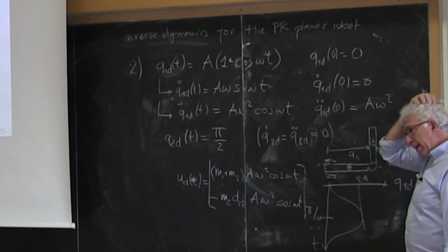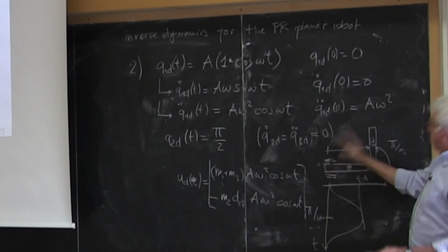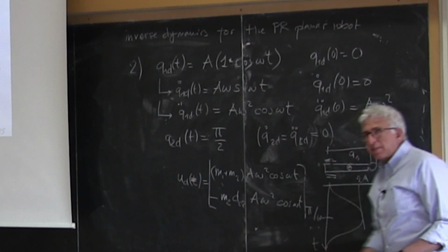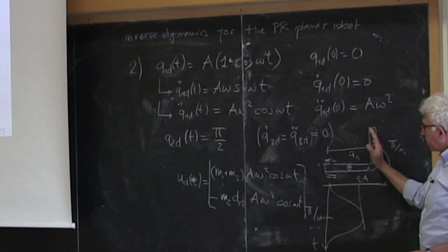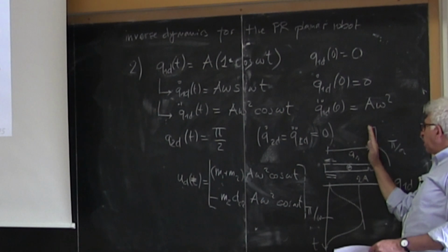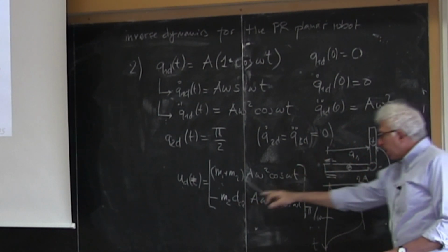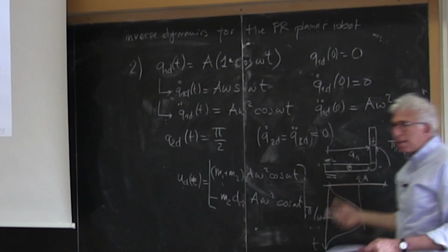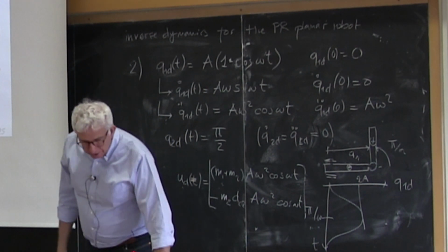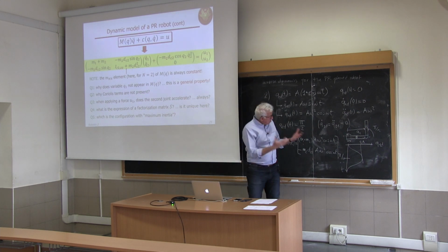So in the counterclockwise, and you need to apply a torque in the clockwise direction, so with the minus sign. Remember, the positive sign is counterclockwise. And vice versa, if you're accelerating in this direction, so with a negative acceleration, this will tend to fall here. You need to apply a clockwise torque by this minus. So minus and minus acceleration, it will be a positive torque. Okay, so you see that this type of analysis is instructive.